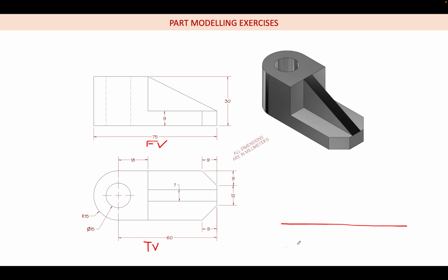So what is the width? So length is 75, width will be, so this is R15, right? So we can do 2 times. So radius of 2 times 15 is 30 mm. So we have to draw first a base which is 75. So you see that this is the 75 length and this is the 30. Okay. So first we will draw this.